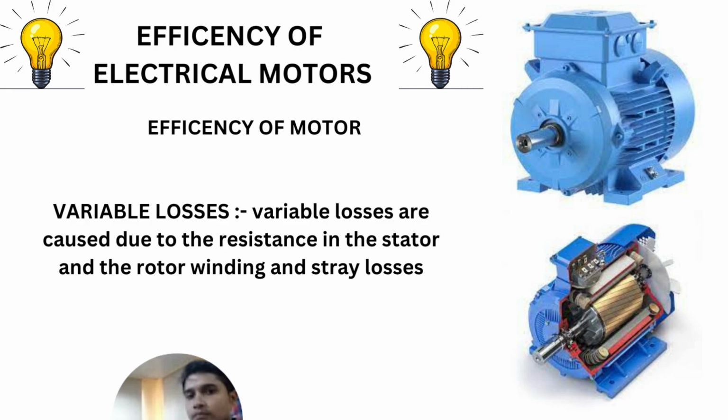The stray loss, according to the IEC standard, is 0.5%, and according to the IEEE standard, it is from 0.9 to 1.8%. Stray loss is very difficult to calculate, so according to the IEEE standard it is considered. And in India, we mostly consider according to the IEC standard, 0.5%.